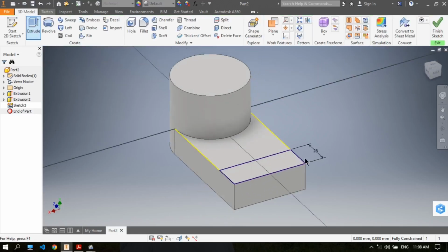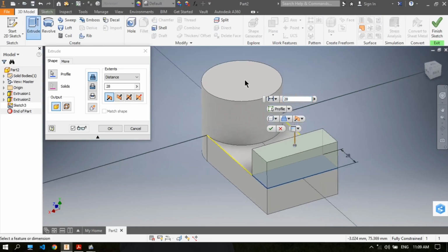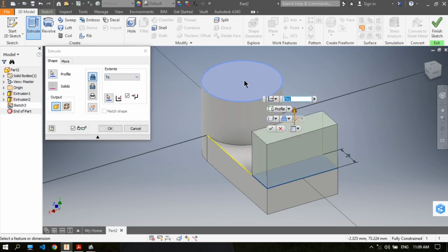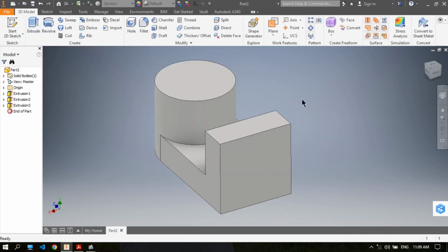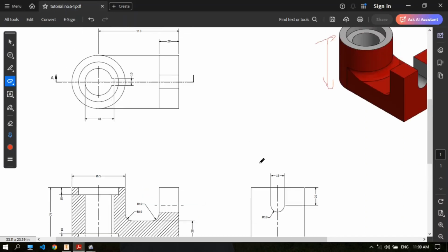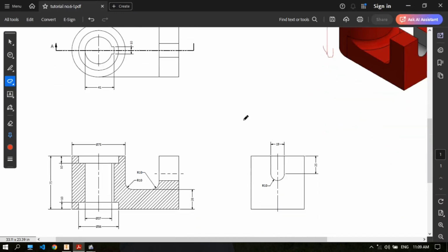Okay, now extrude here, there. This height and that height should be equal. So we choose the two here is 10 and then click the surface. So that means the equal height. Okay, now this is very simple. Okay, now we make a hole in it here, there.